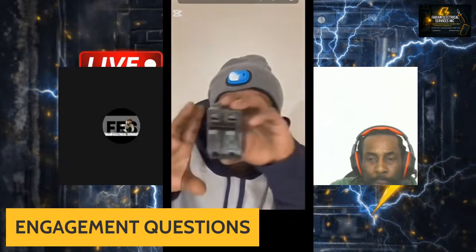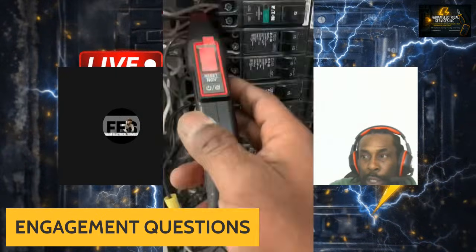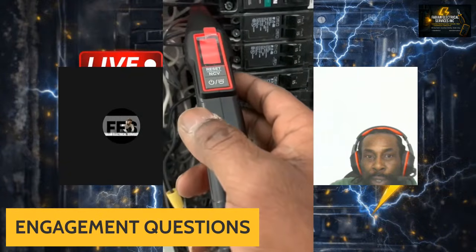Most electricians are using breakers wrong. A breaker protects the conductor, not the device. A 20 amp breaker can only carry 16 amps continuously. That's the 80% rule. Anything running over 3 hours, that's a continuous load.